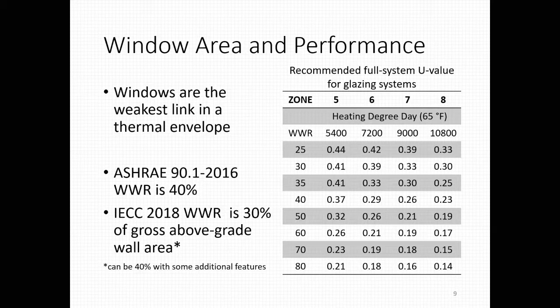And so remember I think I said this on Monday, depending on your building design and what you're trying to accomplish and whether it's residential or commercial, windows are the weak point. So it's always a good idea to get the highest performance windows that you can make a reasonable justification for. You obviously don't want to get super expensive windows and then not have enough money to insulate your building properly.